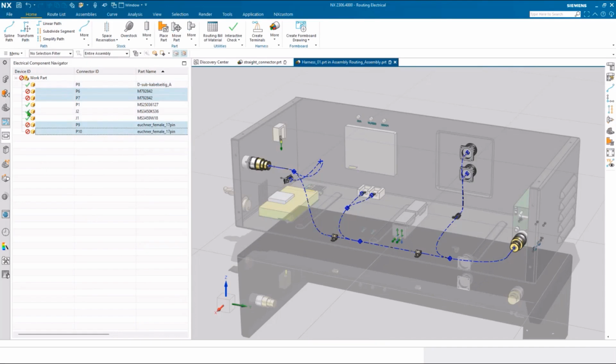All right, so on the left-hand side here, you'll see green check marks. These are the parts that have unique names that NX was able to find, and it identified those. The ones that still have the red slashes, NX did not automatically identify because there are multiple occurrences of those parts. So we need to give NX a little bit of help there to tell which one's which.